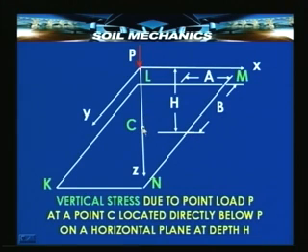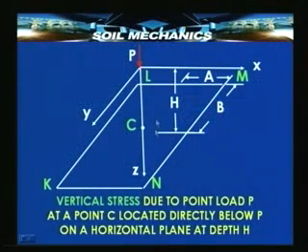If it is directly beneath the load P, if the center C of a horizontal rectangular area is below the point P, then the formula that we have seen in the case of point loads, the Boussinesq's theory based formula, is directly applicable here. That means this is the schematic which can be used for determining the vertical stress due to a point load P at any point C directly beneath P, but on a horizontal plane of finite dimensions. Now, the point C, as I said, could lie away from the center line also.